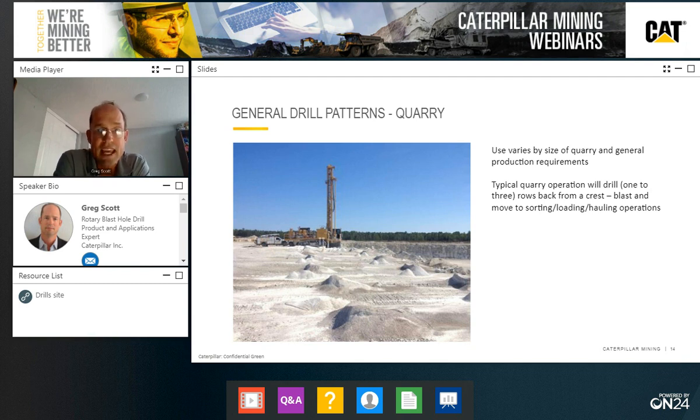In these applications, the CAT rotary blasthole drills have faster overall cycle times because of the ease of setup, positioning over target, leveling up, and then the drill cycle. They've got deeper single pass hole depths, so in all you have fewer cycle counts. I'm able to reach hole depth more often than not in one pass of my rotary head.